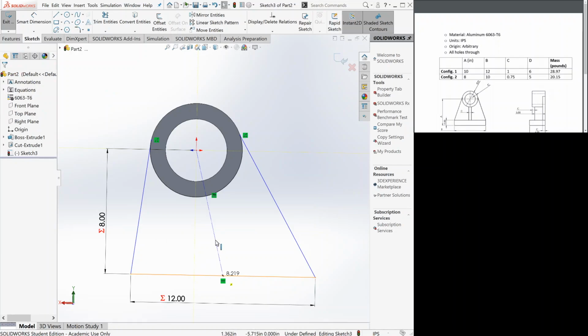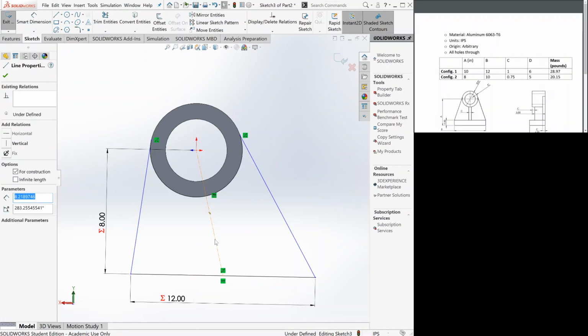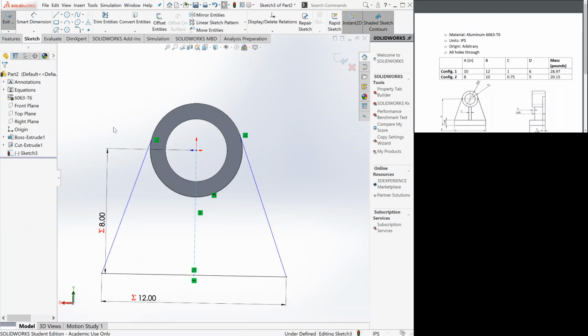Now, again, you can either use control and click on the line and it'll do what we did last time, or you can right click on it. My bad guys, sorry. Right click on it, and there's going to be a pop-up menu, a quick properties tab, and it's going to have horizontal or vertical. Click on vertical. Now your drawing is perfectly symmetrical.